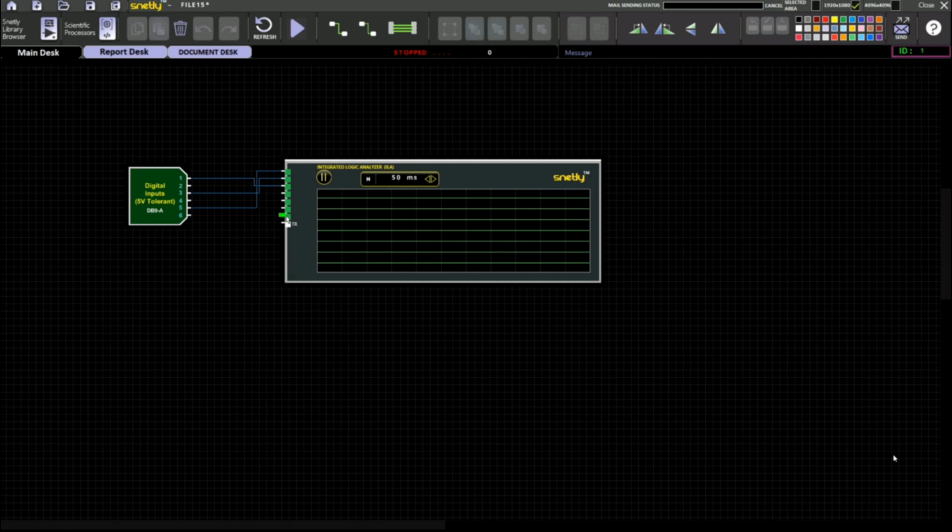By clicking on the run button while rotating the motor we will get the feedback from the motor, high and low. Here high means red color will be indicated, low means it will be in green color. Totally we will get 6 states from 001 to 110, and for those conditions we need to excite our 3-phase voltage source inverter module so that the stator of the motor will get excited and start to run.